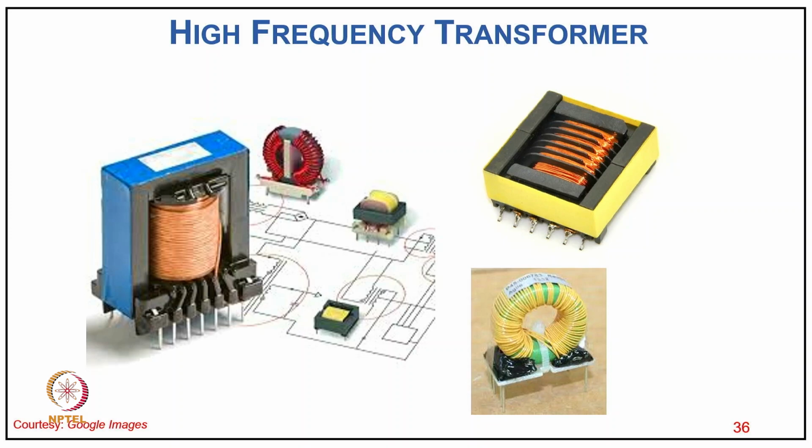switch mode power conversion, radio frequency transformers, welding transformers. There are plenty, including the power supply of switch mode power converters, even LED lighting, then your BLDC fan, and apart from that, instruments, computers, laptops, desktops, as well as the lot of chargers used in all accessories, including mobile chargers and EV chargers. We use the high frequency transformer.